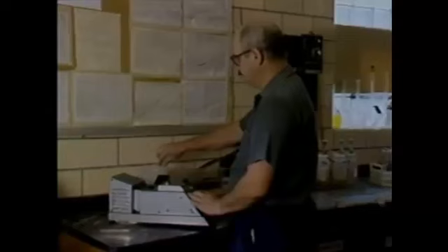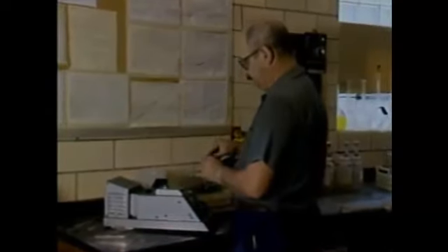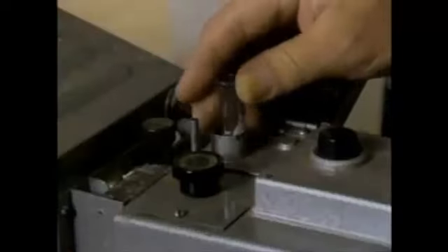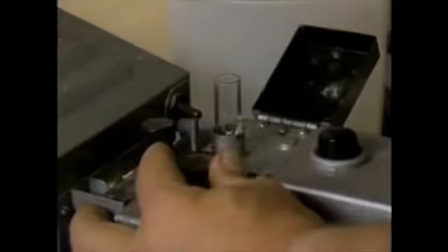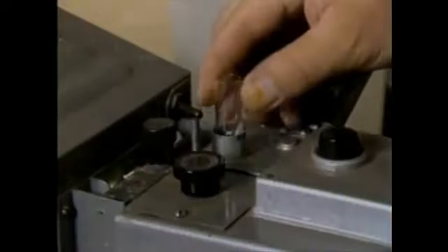A colorimeter measures clarity by comparing the color intensity of the solution being tested to a standard solution with a known color intensity. The standard solution is placed in the colorimeter first, and the colorimeter is adjusted to it. Then the sample solution is put in, and the color intensities of the two solutions are compared. The difference in the color intensities of the two solutions is proportional to the difference in the clarities of the two solutions.